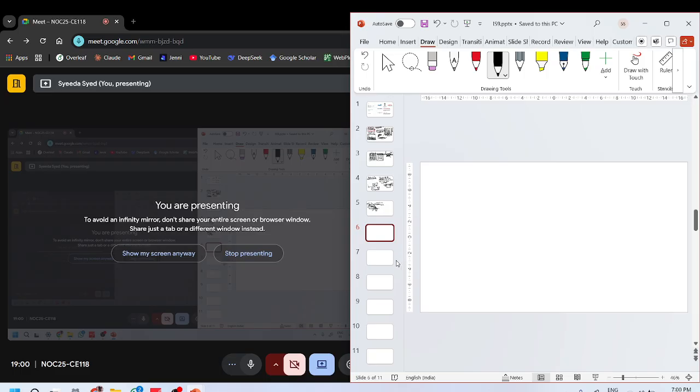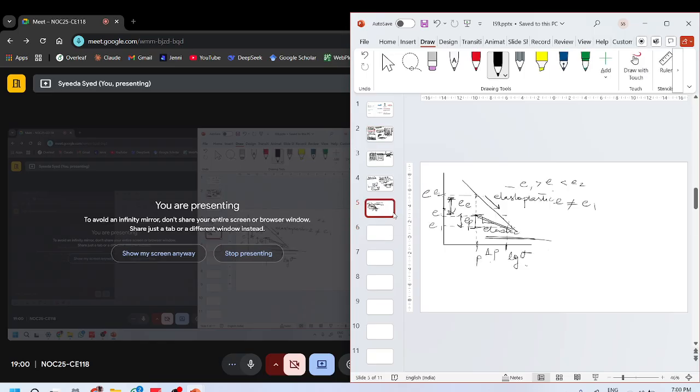Yeah, I saw in most of the textbooks only loading, particularly in the spring analogy model. I didn't see it in the unloading case. The spring analogy we will not extend, but Terzaghi's 1D model we extend by using Cu, Cc, and Cr. We differentiate the slopes of the loading and the unloading line.